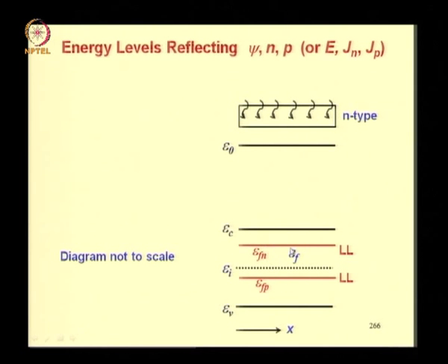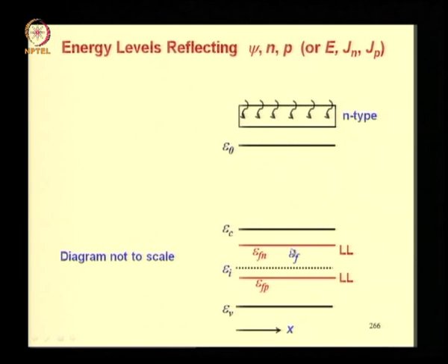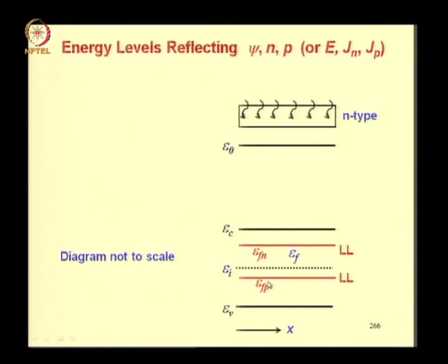It turns out that when the injection level is low, L stands for low level, the quasi Fermi level for electrons is the same as or almost the same as the Fermi level under equilibrium, whereas the quasi Fermi level for holes moves significantly away from the equilibrium Fermi level. Now let us understand why.